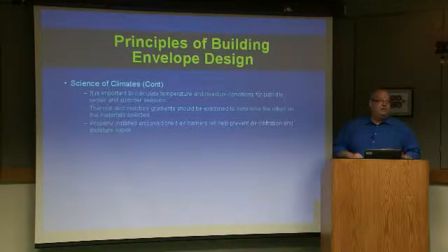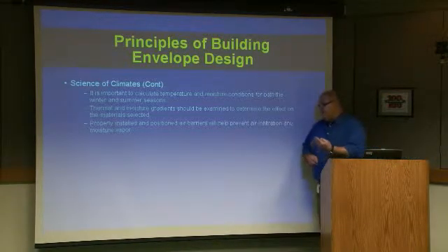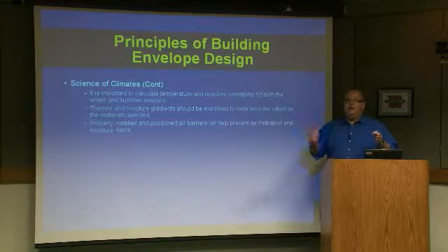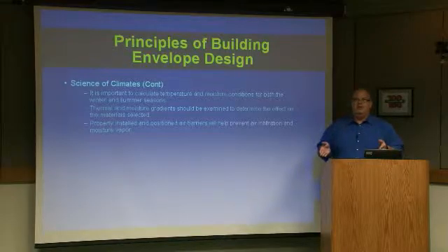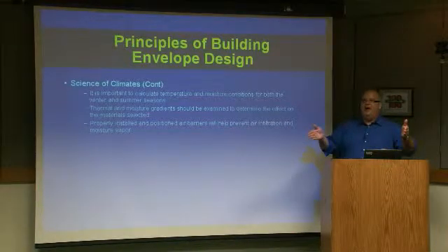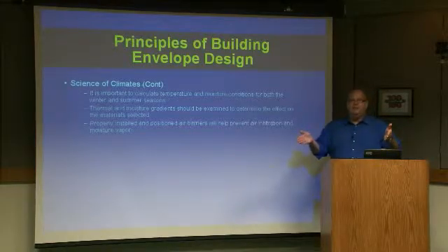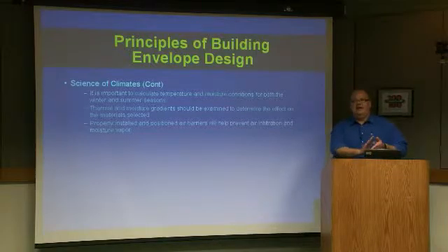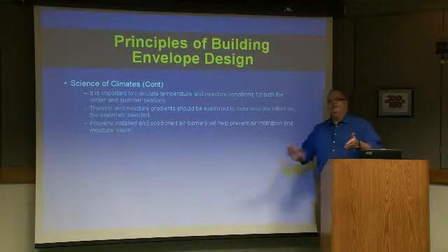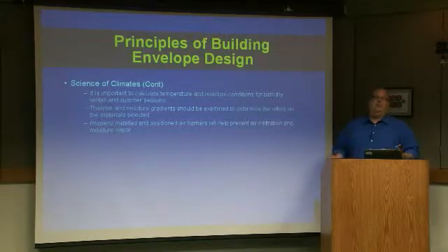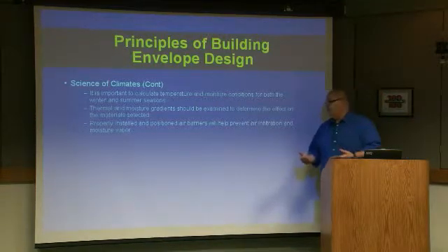One of our traditional uses for an exterior water barrier and air barrier was the peel and stick membrane. If you do that, your interior vapor control's got to be really unique and really tricky. Because you can't have a standard vapor retarder on the inside, or else you've got this double barrier. Again, if water gets in from a leaky window, you're doomed. So how do you prevent that moisture drive in the winter from getting to the backside of that rubber without causing you drying problems? There is a solution, and I can't give it to you now because it is a proprietary solution, but there is a way to do it.